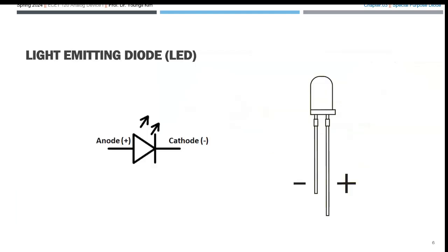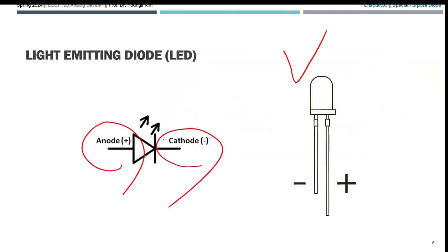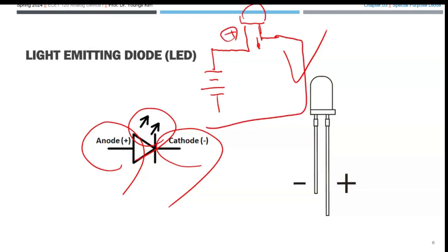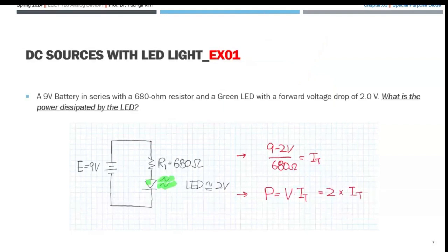Now, that is the LED. We have in the backside red, yellow, green LED. Each LED has, like this one, a long leg. It was plus, the short leg is the minus. So the plus part is the anode, and the cathode is the minus. The symbol is like this one, okay? So when you connect to the battery, the LED long part, and I'm sorry, like this one, short part like this one, plus is the long leg, minus is the short leg. So that was for the 9 volt battery, we learned before, okay?